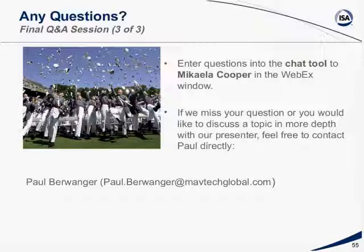It makes sense to split the consoles. I still say you do want to go through the rationalization process, and if that doesn't get you to where you need to be, take a look at splitting the consoles. A lot of times that does happen. You overload an operator with too many unit responsibilities, and you can't reduce the number of alarms without compromising the system itself. And so that's the balancing act. But take a look at splitting the consoles.